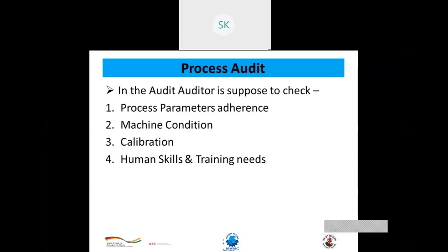I would like to share a few examples. When we are conducting process audits, I have had some good and bad experiences, and I would like to share a couple of them. For one example, I would like to share about the spectrometer die. We normally say there should be at least 2 to 3 dies on the shop floor, because we want to take one die for after pouring and 2 dies on the shop floor for the bath metal. So there should be at least 3 dies, so that whenever we pour the metal, the die is near normal or atmospheric temperature.